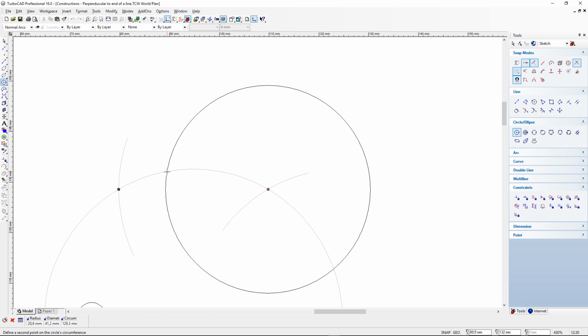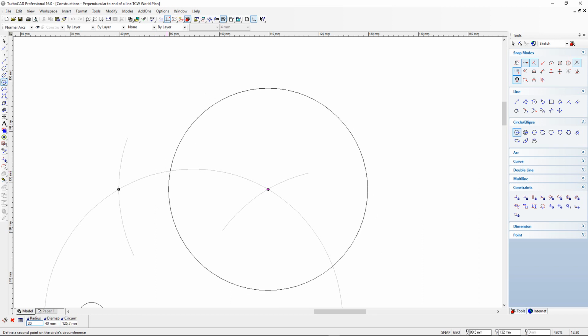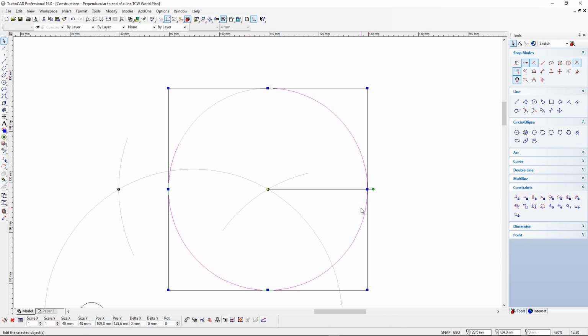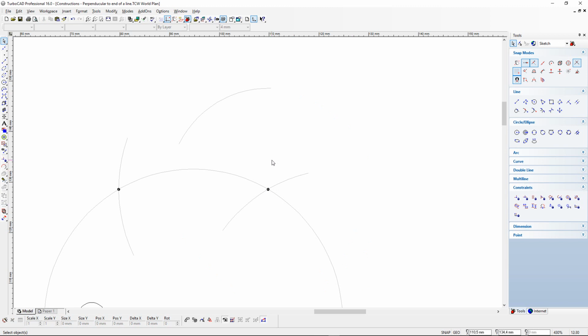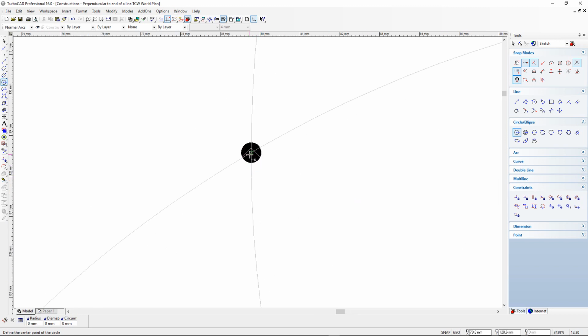So I'm going to stretch it to 20 millimeters and draw a light construction arc with a radius of 20 millimeters. Once again, I don't need the full circle, so I'm going to cut off parts of this arc and erase the parts that I do not need. We call this clutter on our paper, and doing the erasing of the excess lines, we can also refer to that as housekeeping.